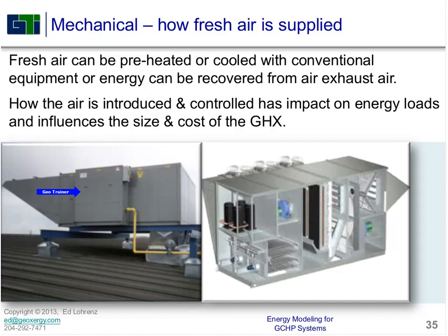Turn that into a cooling dominant building even in a fairly northern climate. And then use this as much as you need to. Sometimes, in some cases, you can actually put a hydronic coil in parallel with or in series with the gas rooftop unit and use that to help balance the loads as the system operates from year to year.